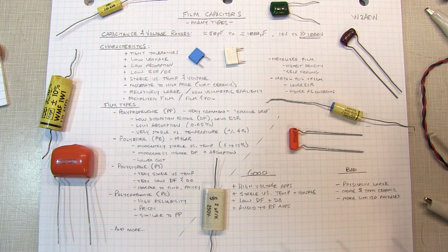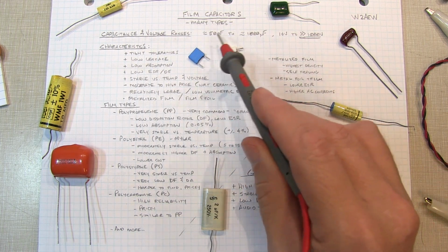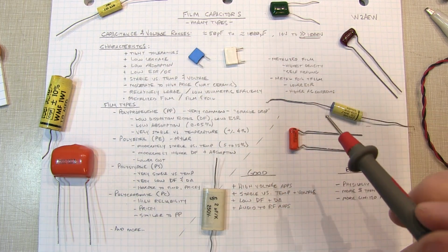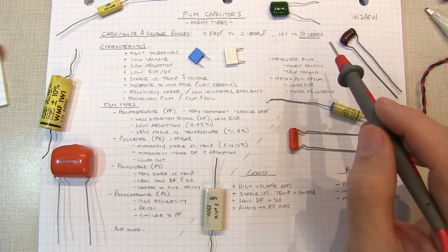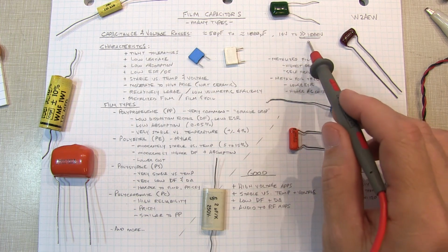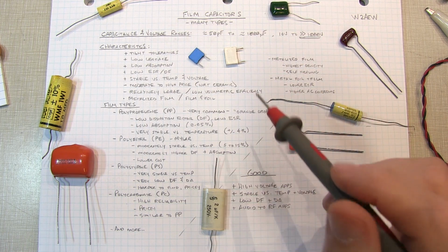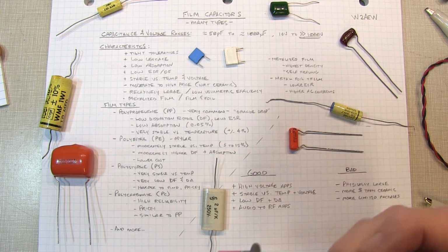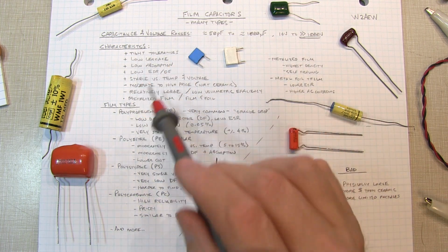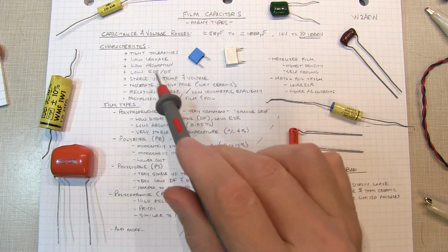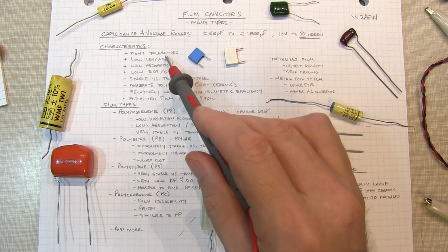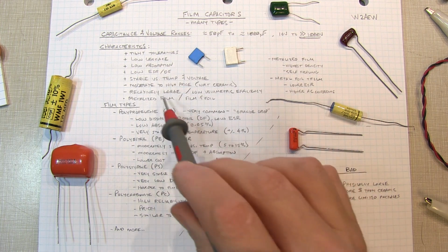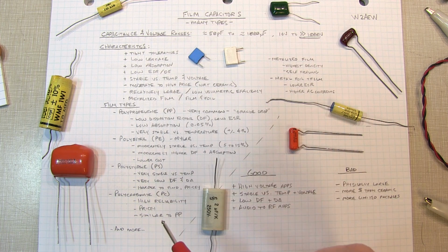So some of the things that film capacitors have in common is that they're generally available from the low tens of picofarads to in the neighborhood of even 1,000 microfarad, very large values, and working voltages from relatively low voltages to well over 1,000 volts. So very wide capacitance and voltage range. Generally, the film caps have really tight tolerances and very low leakage, very low absorption, very low ESR and dissipation factor. All really good characteristics for capacitors. They're very stable with temperature and voltage, but they're moderately to highly priced with respect to ceramics.